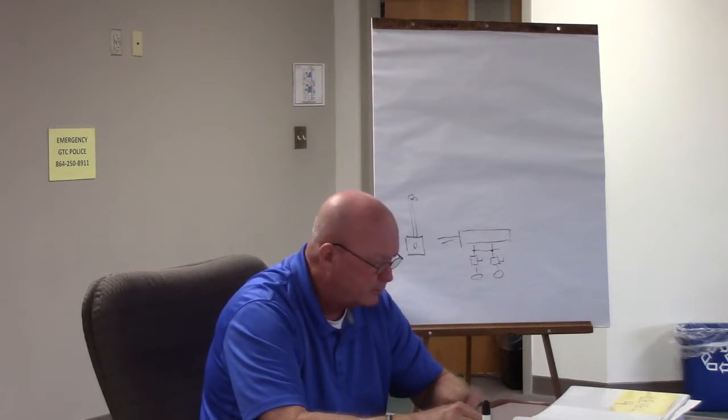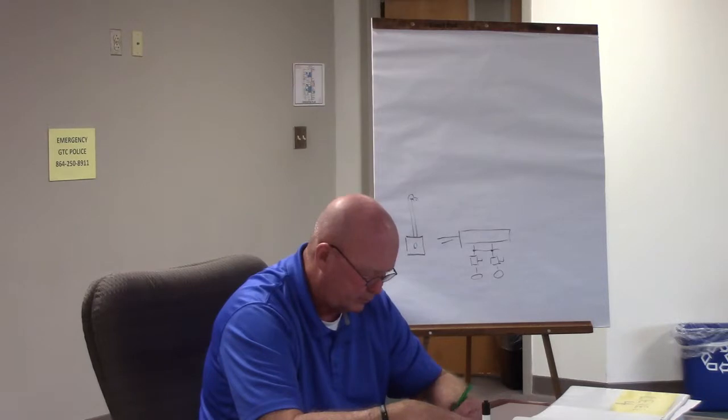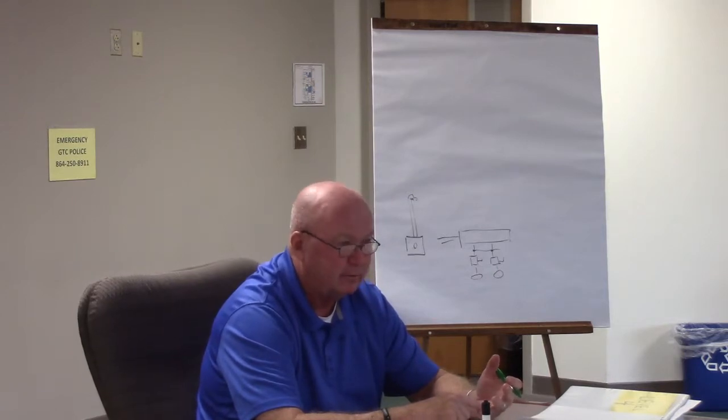The minimum feeder circuit conductor size, before the application of any adjustment or correction factors, shall have an allowable ampacity of not less than 100% of the non-continuous load plus 125% of the continuous load. So that's the thing to remember: we always have 100% of the non-continuous load and 125% of the continuous load.